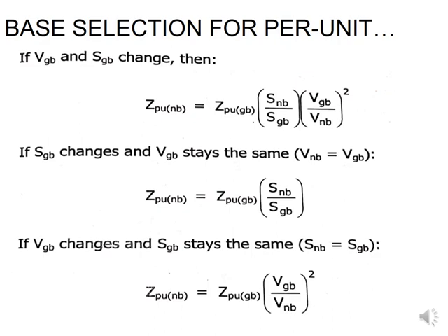So you can see with what I was saying on the previous slide now, here you have an equipment that is already at per unit. Okay, so it could be a transformer, or it could be a generator, or it could be a motor, but it's already in per unit because they've changed that impedance into a per unit. You still need to change it into a per unit on the new base. And this is how you would then do it.